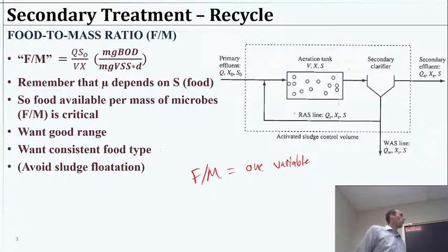We would hope that we don't have a sudden spike in pH one way or the other, or sudden, normally we get sewage and then suddenly we're getting a whole bunch of oil and grease from restaurants or something, who knows what. If something like that would happen, there's potential for different types of bacteria to start growing and you can get some that like to form more filamentous, floaty type stuff, and then you have a whole bunch of mass escaping, and that's bad news.